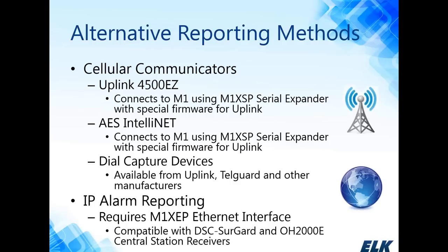We can integrate with the AES and Telenet radio. Once again, it takes the XSP module. There are also a number of dial capture devices on the market today which simulate phone line voltage and current to a security system, and the security system sees the phone line, dials the number, and transmits data. The dial capture module would capture this information, turn around and relay it out through their network.